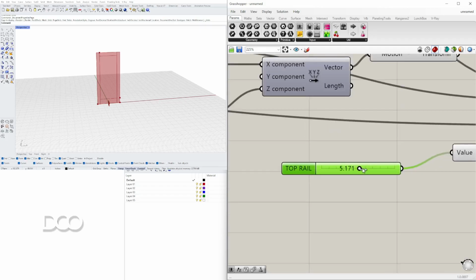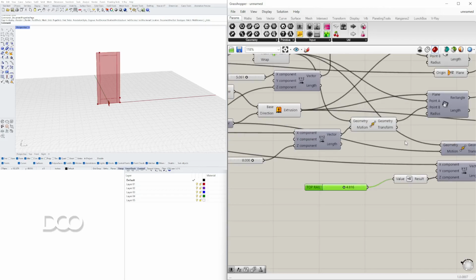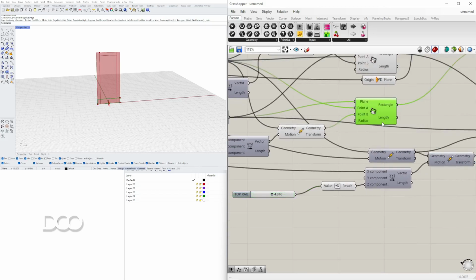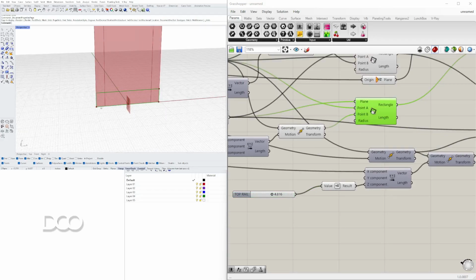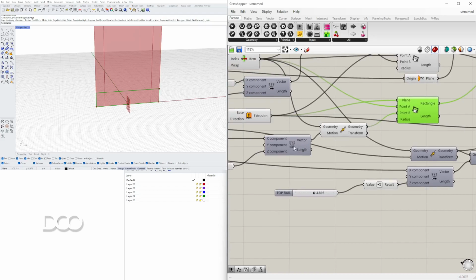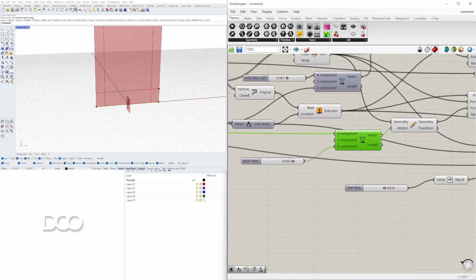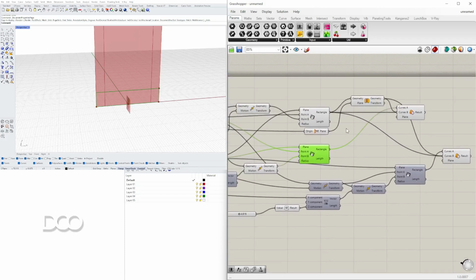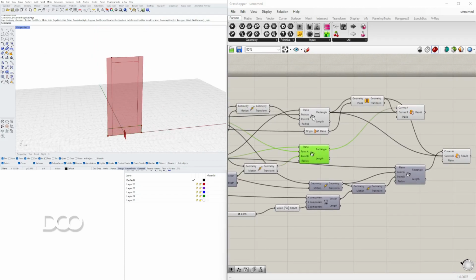And the way that I created these was using this particular component called Rectangle 2 Points. So what I did was I extracted this point, moved it up using a vector, and this then creates this overall rectangle. Well, since I had already created the side rails here and here mirrored through the center, what happened was I used a region difference.